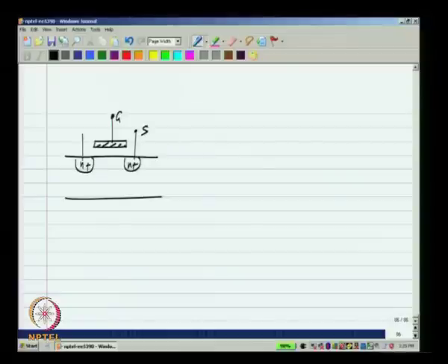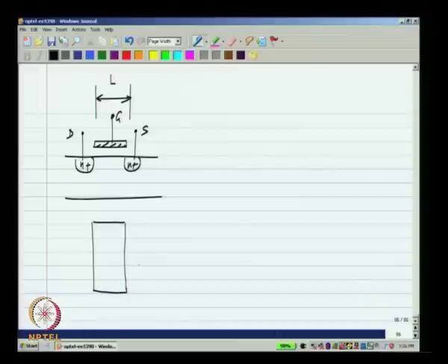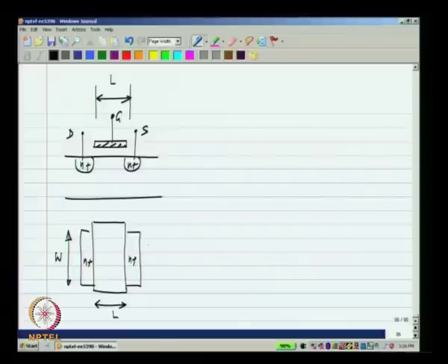As usual, this is the gate, source and the drain, and the distance between the drain and source is the length of the transistor. And if you look at the top view of this device, there is a certain width for the source and drain regions. Okay. So, the current flows across this width, and that is the width of the MOS transistor.